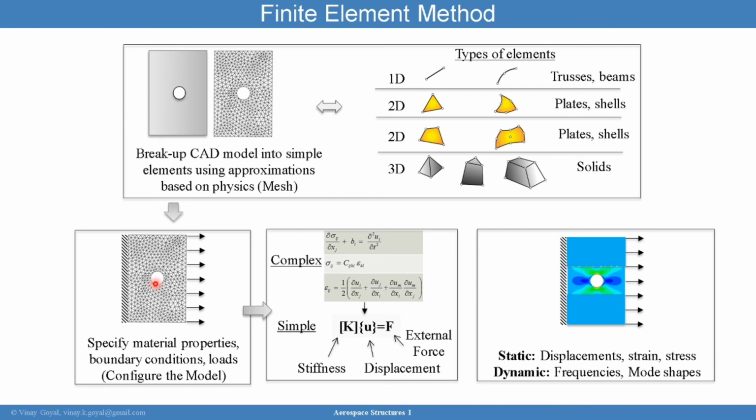And what we're really doing with the element formulation is that we're taking these 15 equations, these highly coupled partial differential equations, and putting them in this form: stiffness times deflection equals external force. Now, this is a mathematical miracle. Why? We've taken complicated equations, very complicated to solve by hand, and put them into a linear algebraic form that can be solved quite easily.